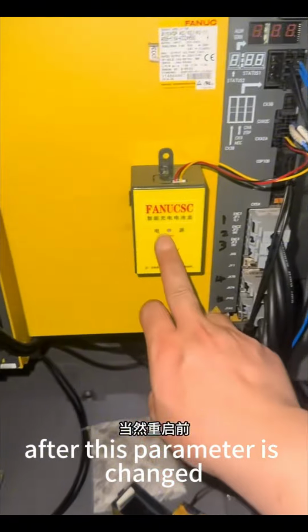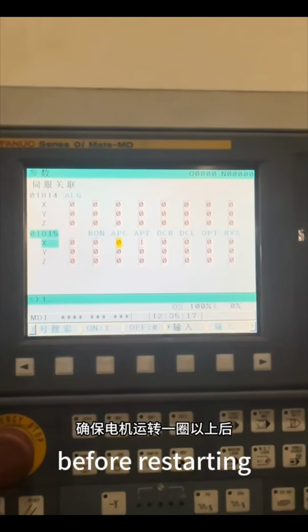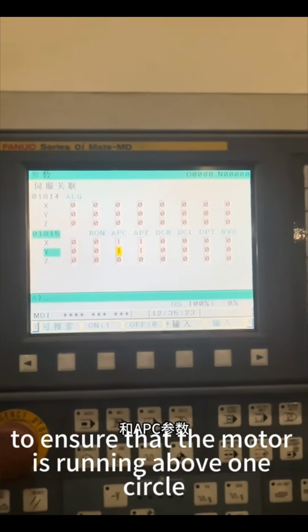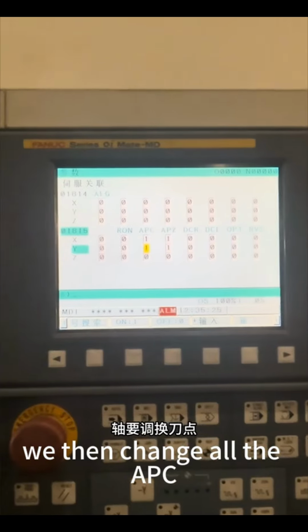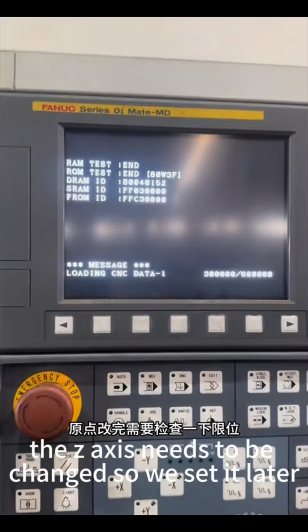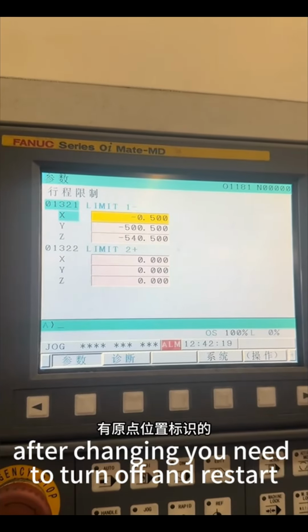After this parameter is changed, you need to turn off and restart. Of course, we need to change the new battery before restarting. Then we move the X and Y axis to ensure that the motor runs more than one circle. We then change all the APC parameters of 1815 to 1. The Z axis needs to be changed separately, so we set it later. After changing, you need to turn off and restart.